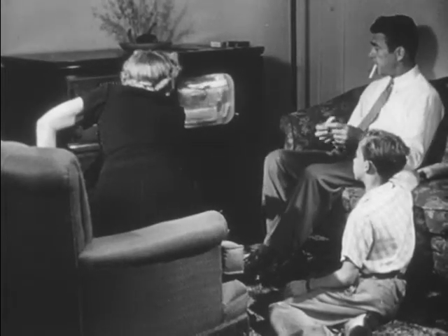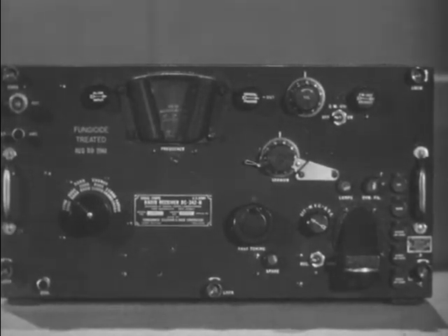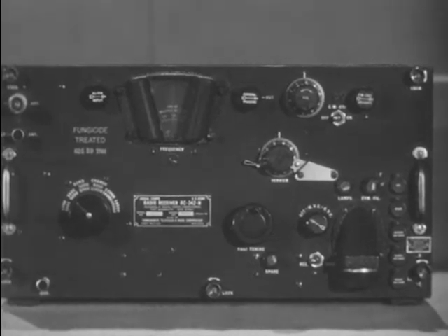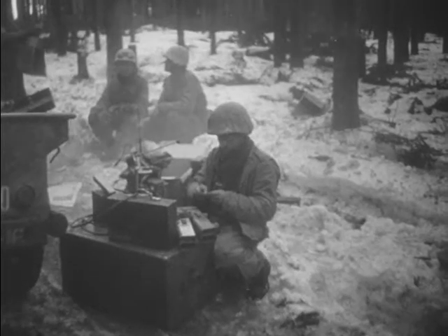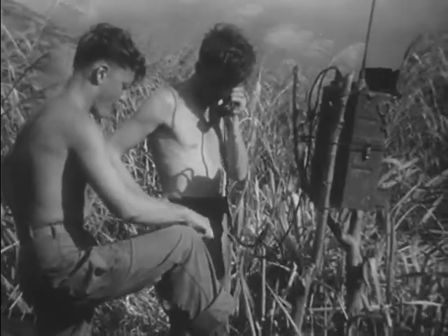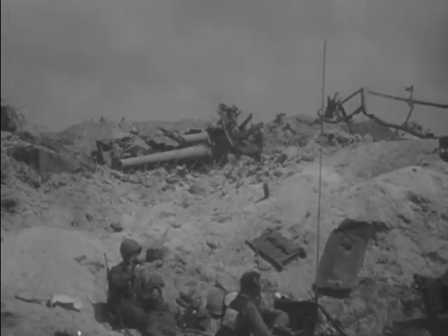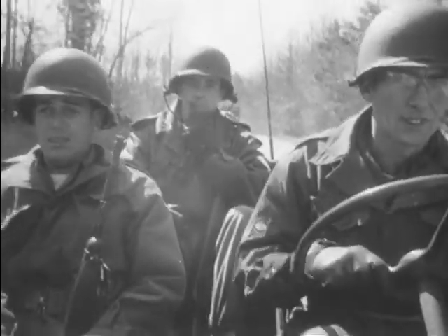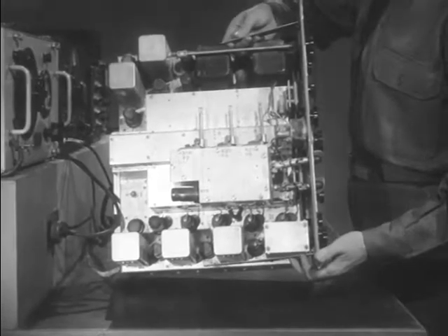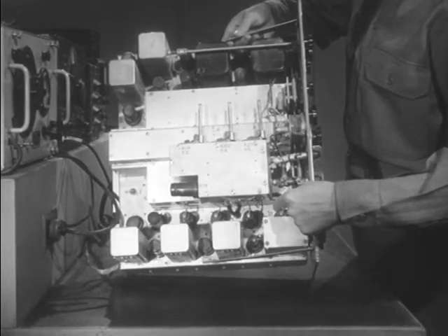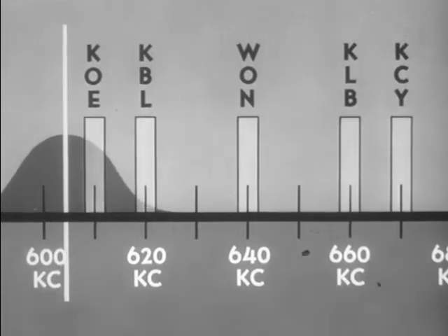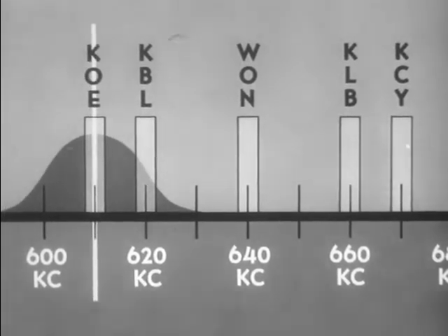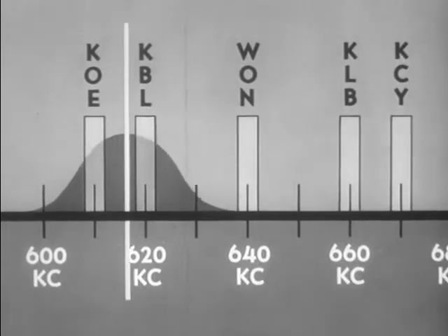Any receiver, whether it be a television or broadcast set, a military radio or radar receiving set, must be tuned accurately to the same frequency as the transmitter to allow reception of the signal. Weather changes such as cold, heat, or dampness, jarring or vibrations, variations in tubes and other factors affect the tuned circuits in all radio receivers, causing loss of sensitivity, selectivity, or ability to separate stations or frequencies, or loss in signal strength.